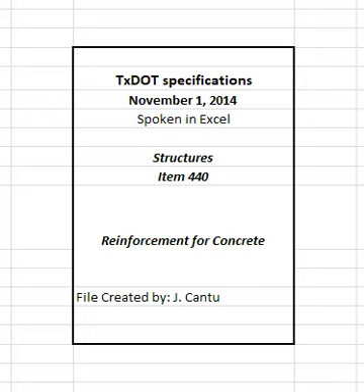3.4 Splices. Lap splice, weld splice, or mechanically splice bars as shown on the plans. Additional splices not shown on the plans will require approval. Splices not shown on the plans will be permitted in slabs no more than 15 inches in thickness, columns, walls, and parapets. Do not splice bars less than 30 feet in plan length unless otherwise approved.